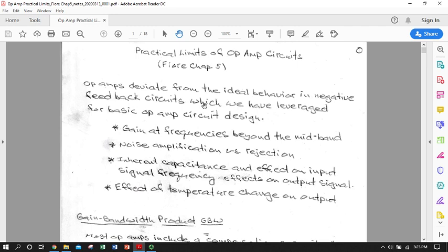It was great. And we were able to make some great bomb-proof assumptions about idealized op-amp behavior, namely that both the inverting and non-inverting terminal had infinite impedance, so no current flowed into them, and that allowed us to also say that the potentials at both were the same.